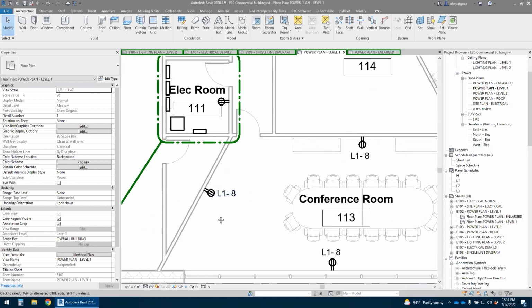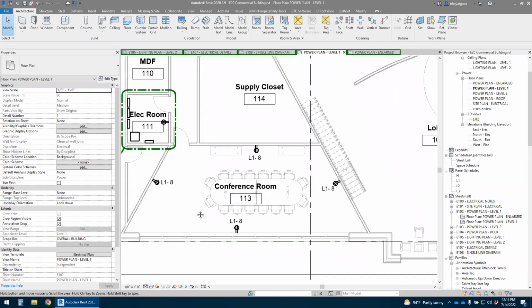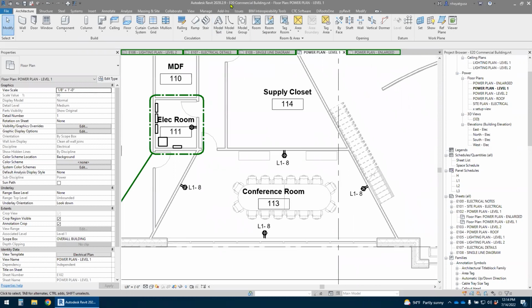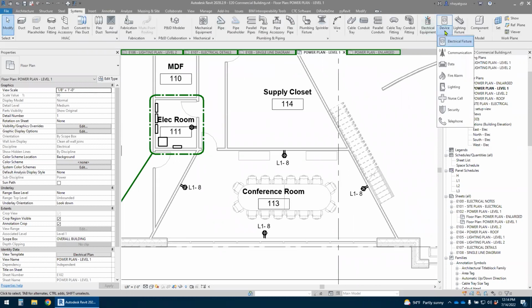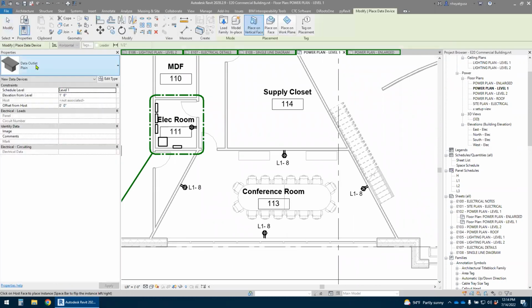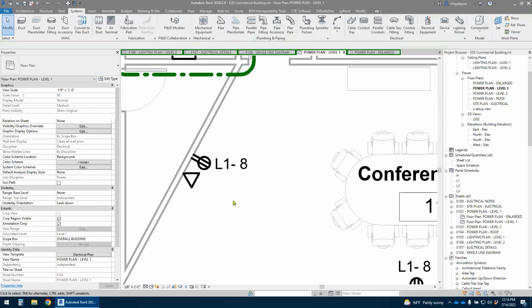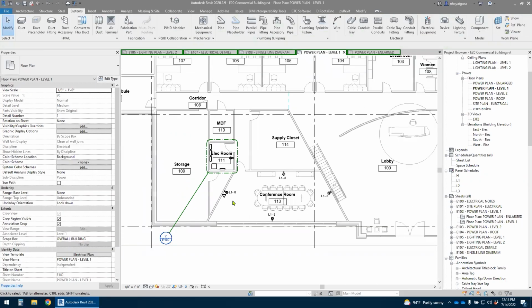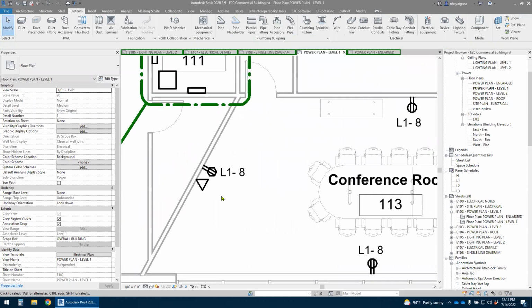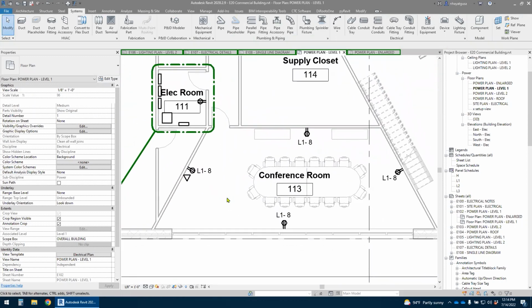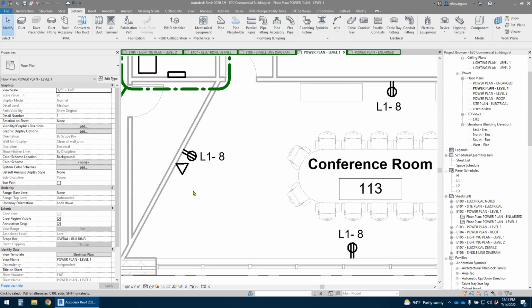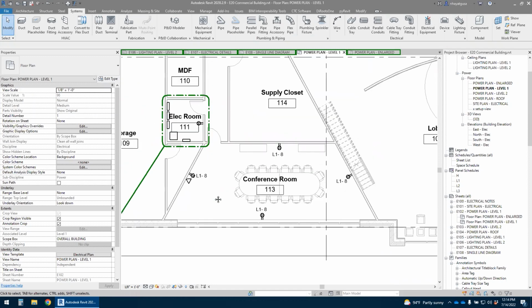Let's say we've confirmed with the architect that the TV is going to be up against this wall and not this wall. So we go to Systems, Device, Data, and they don't give us any options. So we get plain, which is fine. We can just stick it on the wall right there. Now we do have to have a symbol legend somewhere, and that's not covered in this, but basically you need to tell them a triangle is, for the electrical scope, provide J box adjacent to nearest receptacle with 1/2-inch conduit and pull string to above ceiling, that kind of note on there.